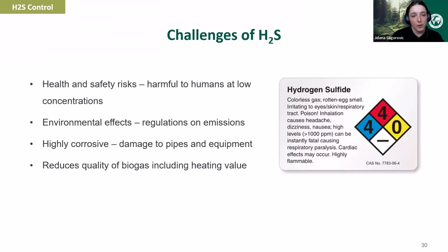So I want to talk about the challenges of H2S. So H2S, of course, has health and safety risks to humans and operators. It's heavier than air, so it goes into low-lying areas, which can be a danger for operators. It has environmental effects. It can help produce acid rain.